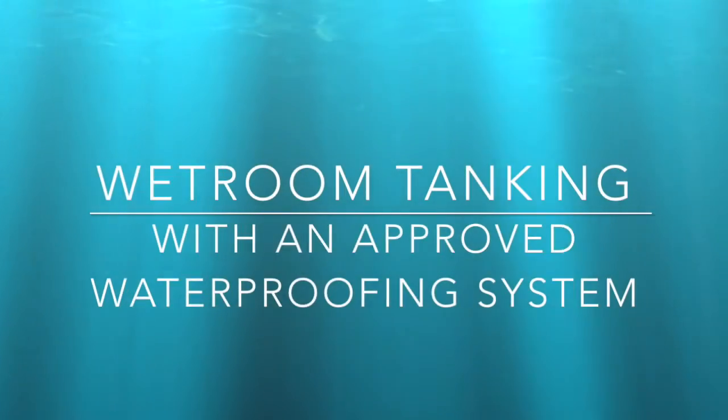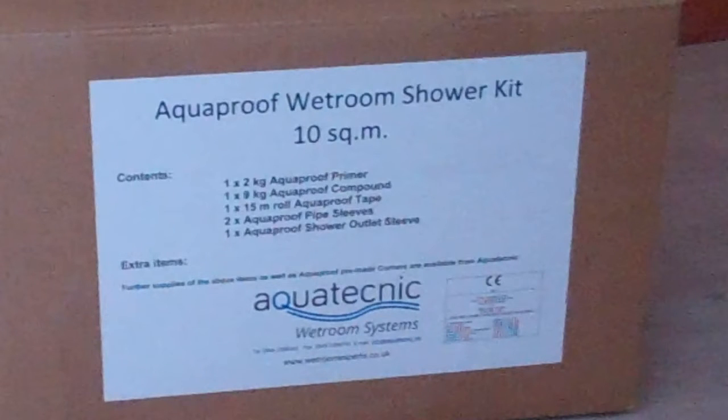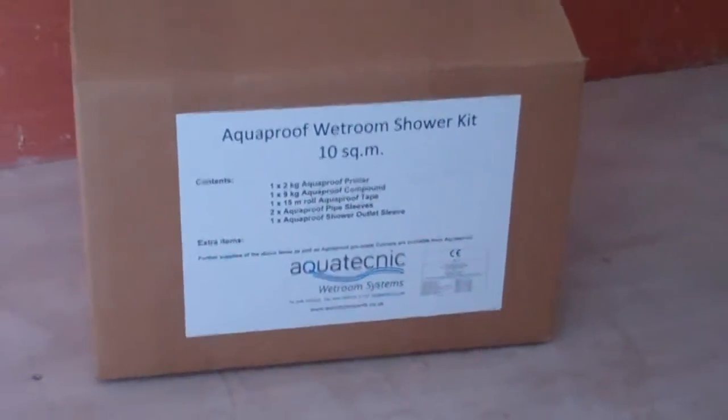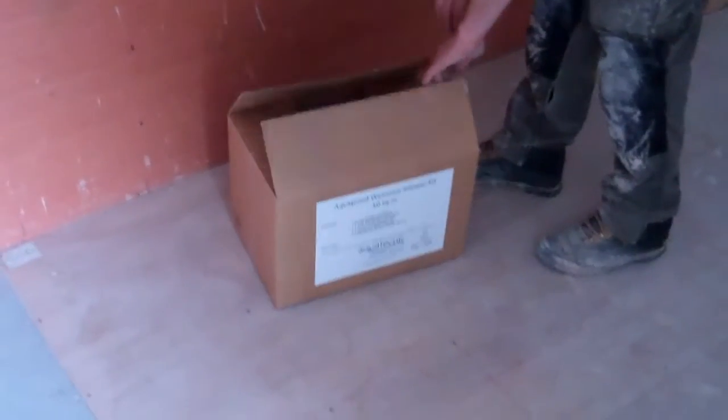Wet room tanking with an approved waterproofing system. All tiled wet rooms must be waterproofed with a CE marked approved wet room tanking system. Aquaproof system has a European technical approval specifically for the waterproofing of wet rooms. The Aquaproof system is available in kit form or as individual components.